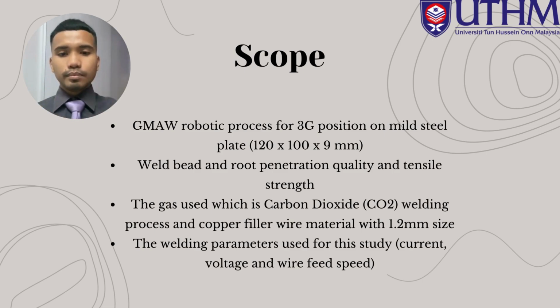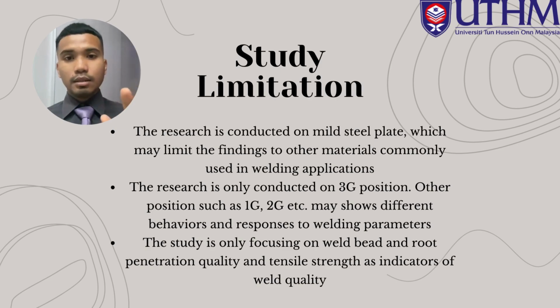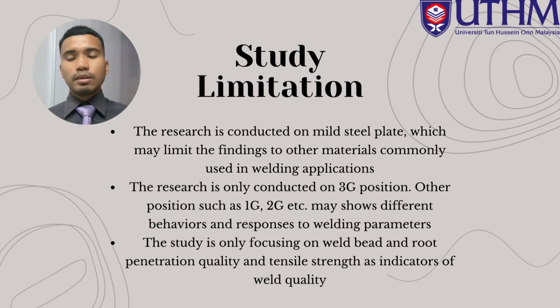speed. So for my study limitations, the first one is my research is only conducted on mild steel plate, which may limit the findings to other materials commonly used in welding applications such as aluminium and stainless steel. The second one is my research is only conducted on 3G position, so other groove positions such as 1G, 2G, 4G, 5G, and 6G may show different behaviors and responses to welding parameters.